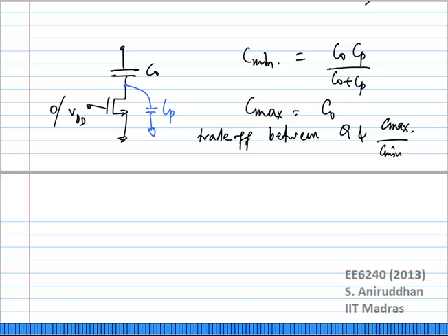Okay? So now what we have said is we need to get a certain phase noise performance by minimizing KVCO, right? That's where we started off. We want to minimize KVCO. We want to get a certain tuning range for that given phase noise. Okay, what next? Are you done now? Sure, you are more or less done now, right? You have designed the transistors, you have designed the LC bank. Okay, what else you need to do?